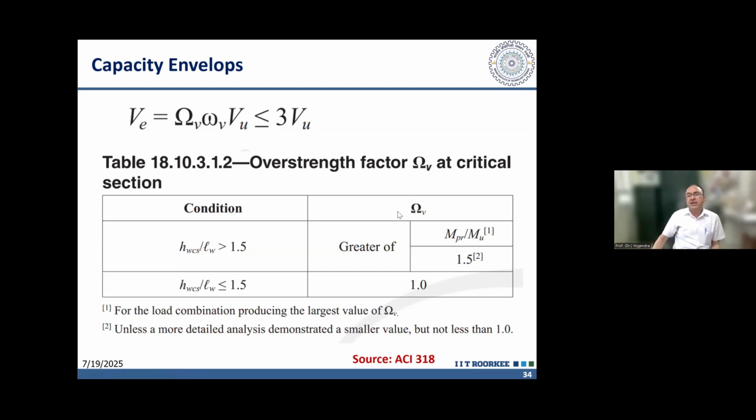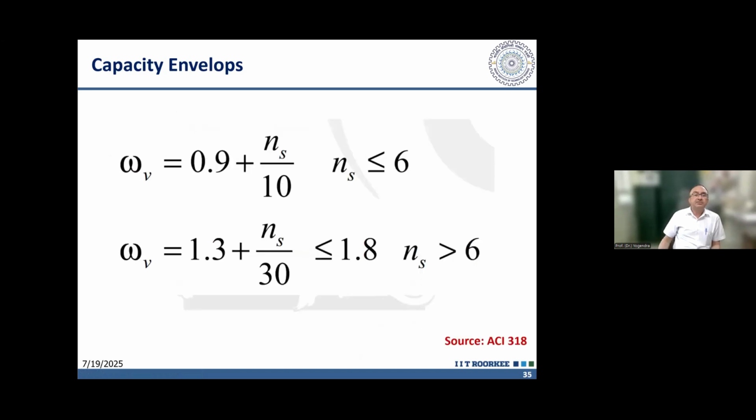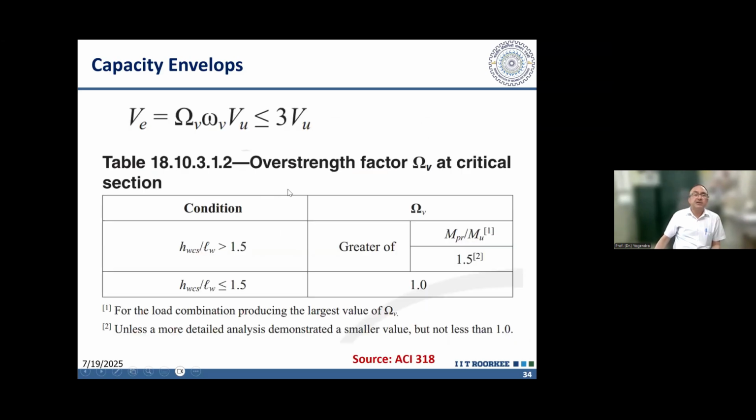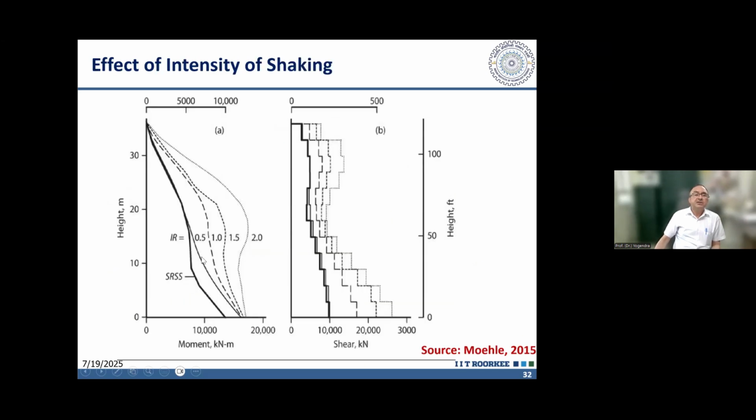reinforcement. And generally we end up providing more reinforcement, more vertical reinforcement in the shear wall, and this factor is anywhere between 1.5 to 2, or maybe even more than 2. So this factor is to be considered. So capital omega is taking the actual ratio, the overstrength which we have provided, and this omega v, small omega v, this is considering the dynamic amplification factor. What is the dynamic amplification factor? Because of the change of the mode shape and the bending moment diagram.